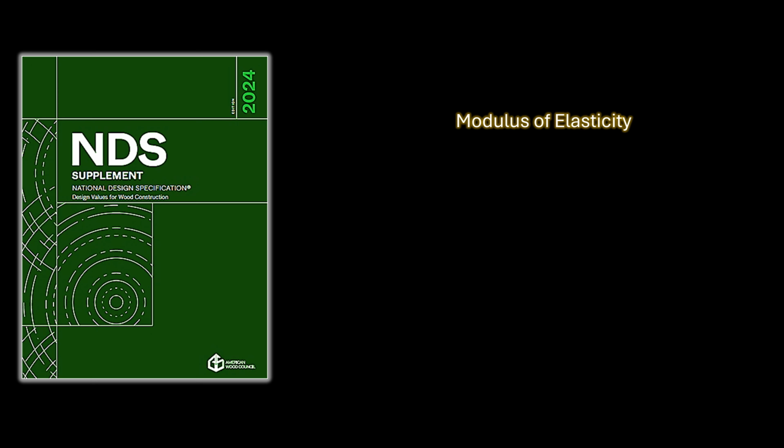The modulus of elasticity used in deflection calculations is a material property of the species of lumber used. Modulus of elasticity values used in deflection calculations are provided in another publication of the American Wood Council known as the NDS Supplement. A link to a free copy of the NDS Supplement provided by the American Wood Council is provided in the description. The NDS Supplement provides design values known as reference design values for nearly all species of lumber that are commonly used in construction in the United States.